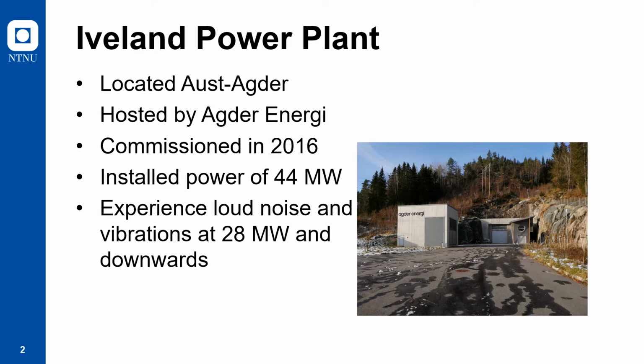The new plant has an installed power of 44 megawatts, exploiting a head of 50 meters and a flow rate of 100 cubic meters per second. The new turbine is experiencing loud noise and vibrations when running at loads beneath 28 megawatts, and they have asked for help to find out what the cause of this is.